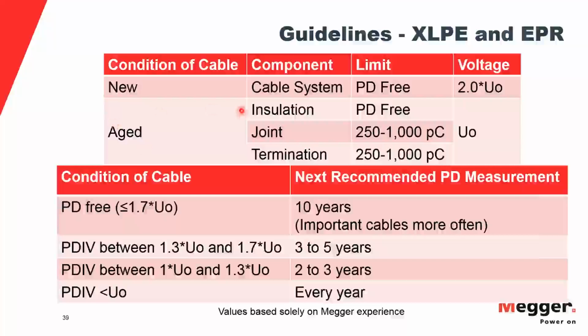You have to consider that the insulation material is constructed completely differently. Extruded cables are a single extrusion. They're rubber cables. Whereas a paper lead cable has wraps of paper, upwards of 100 wraps around. It actually takes a little bit of effort for the partial discharge to jump these layers. So it has to jump hundreds of layers, and each one of those takes some effort. So you can have some very high PD values with a cable that's actually pretty reliable.